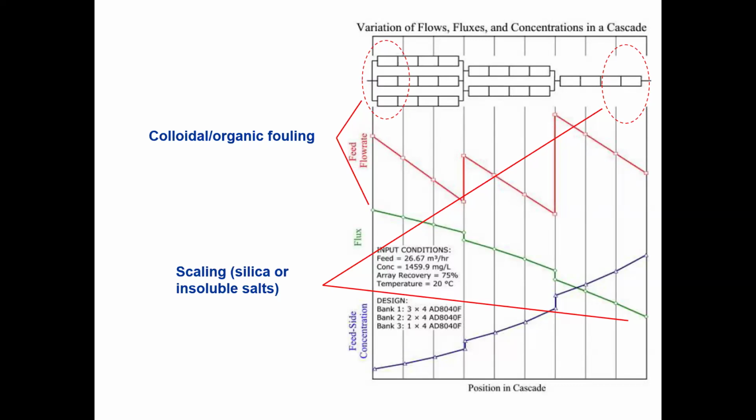And you have a high concentration of inorganics, like iron and manganese. Your pure water keeps being produced, and then you have a brine. At the end of your element, there are a lot of inorganic compounds at very high concentration compared to the first stage. At the last stage, your calcium concentration is double, sodium concentration is double, even silica concentration is double.